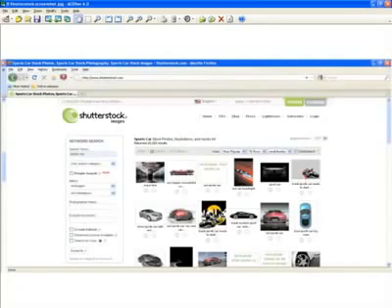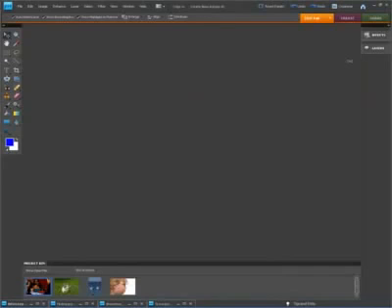Low-res graphics tend to produce very poor quality, and that is going to be the case if you end up using a low-res graphic. For example, if you have a 1-inch by 1-inch engraved object, the resolution of that object needs to be approximately a half a megapixel. As you go up to, say, a 4 by 6 inch engraving, you need to be approximately 2 megapixels, all the way up to about 12 by 12, where you need to be right around 8 megapixels. So the higher the resolution of your graphic, the better the overall graphic quality output is going to be.